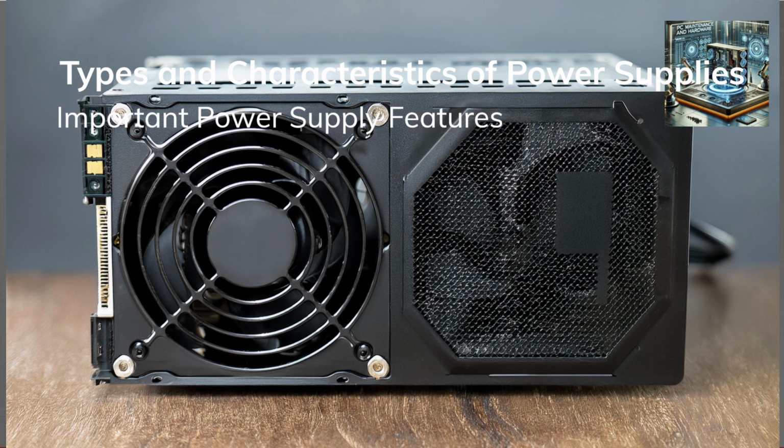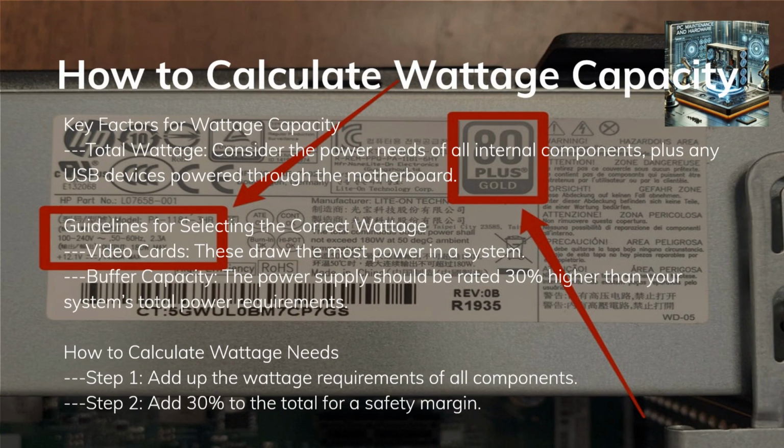which has two identical power supplies for backup in case one fails. When selecting a power supply, it's important to consider the total wattage your system needs. This includes not only the components inside the case but also any USB devices that draw power from the motherboard. Two key points to remember.